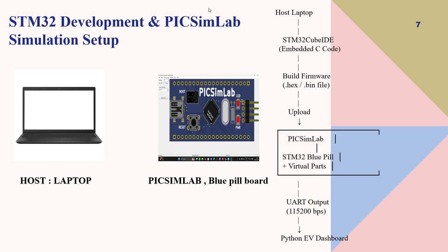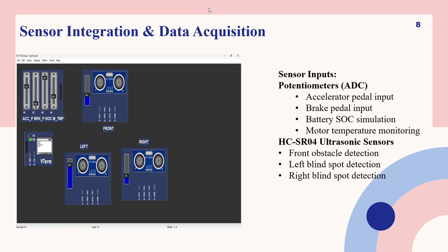Next, I have implemented the Python dashboard. Next, sensor integration and data acquisition. These are the module spare parts in PICSimLab. This is a potentiometer. Potentiometers are used as ADC inputs for acceleration pedal input, brake pedal input, battery SOC simulation, and water temperature monitoring.